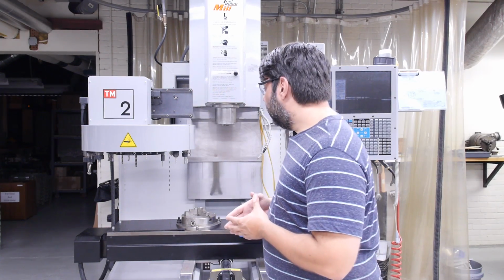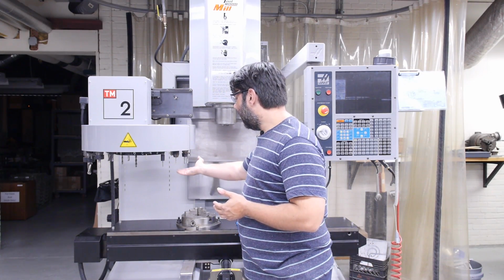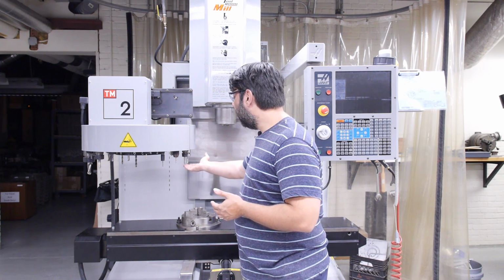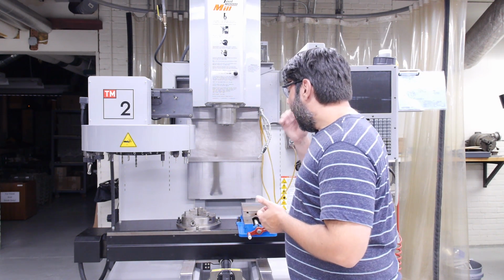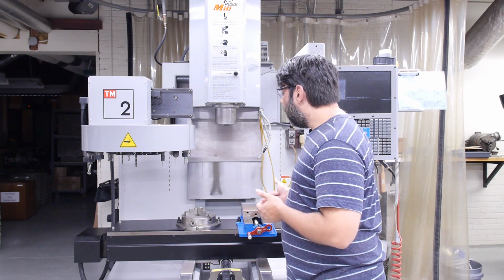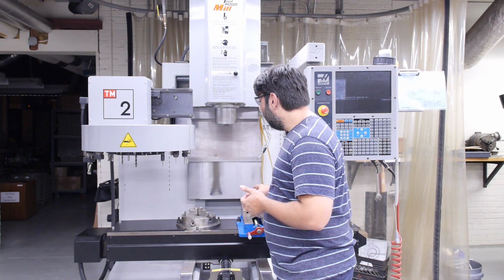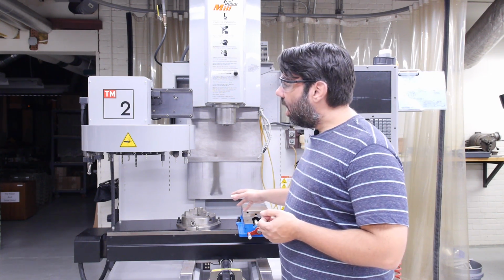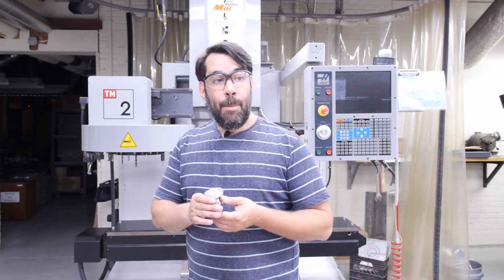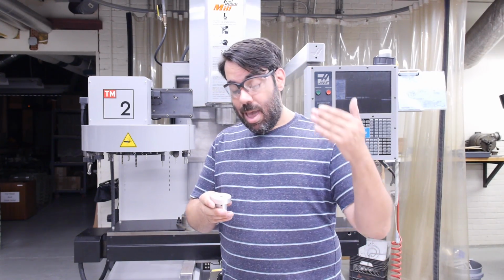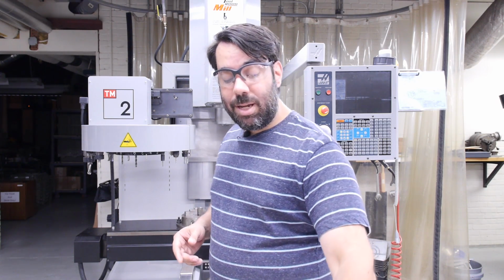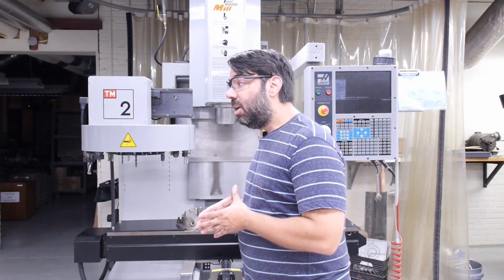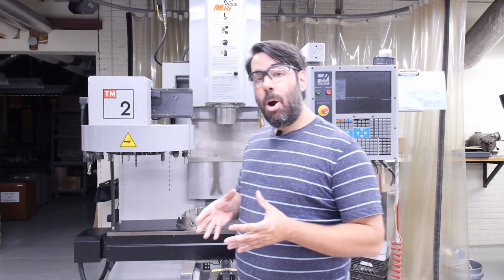The time that it takes to load the tools and teach the CNC machine how long they are and what size they are, as well as write the program, debug the program, and then carefully run the program the first time when they're making that part, often requires more time than simply taking the simple part, moving over to a manual machine, and either producing the part or the required features. Okay? So a CNC machine can actually be slower and more expensive to make low quantity, simple parts on.